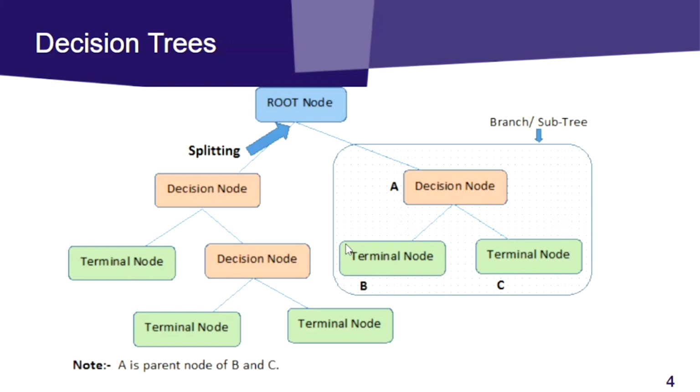Decision trees are a good alternative to optimize logic functions because tree-based methods are adequate for classification problems, which is the case of Boolean functions. Also, decision trees are convenient solutions since their outputs can be easily transformed into a sum of product or product of sums function. And lastly, the algorithms for building decision trees are usually fast since they do not require expensive operations. These decision trees are formed by split nodes, which is a comparison between features and constants, and leaf nodes, that are the final outcomes of the model.